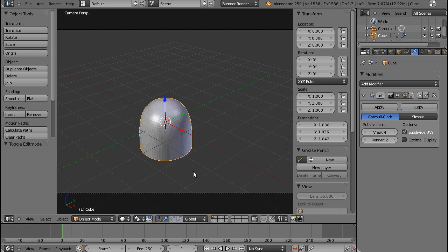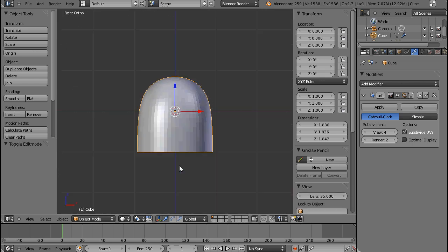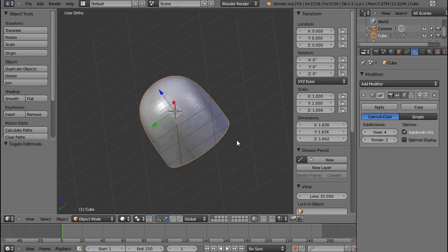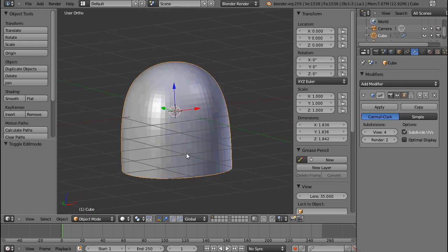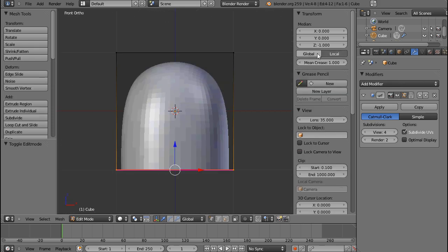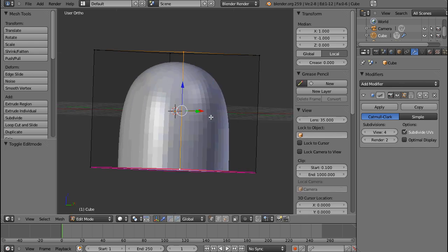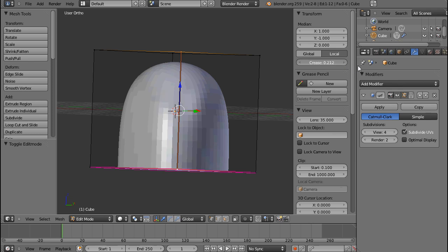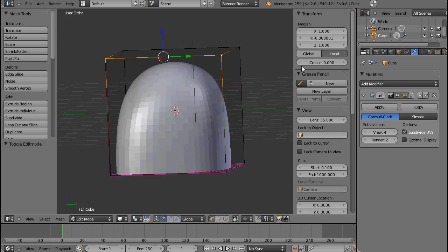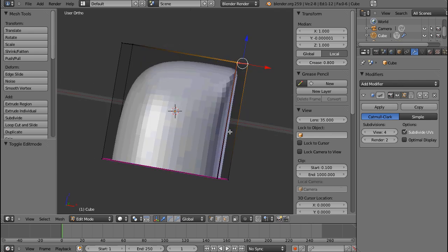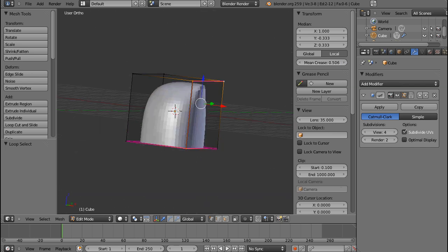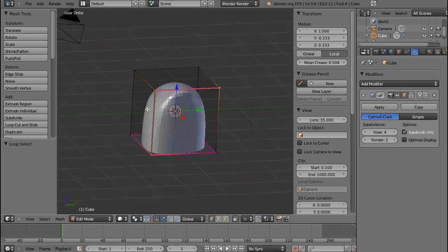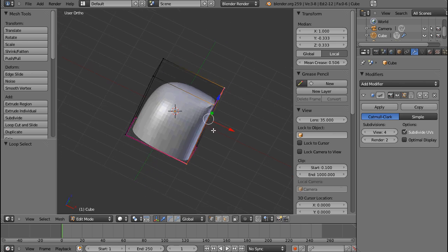So this option is actually really good if you want to keep your polys low, and actually it creates a perfect straight edge, which also is very important. Well, sometimes. And the only downside to the crease is, let's say I make this edge here a crease of 0.2 or something, and this edge gets a crease of 0.8. Then if I select these two edges, I get a mean crease of 0.506, of course. That's the mean. So if I have an entire loop with different crease strengths, then it's going to be hard to control that later on.